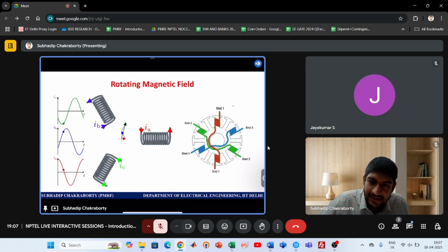And just for animation, we have seen in the previous week also the phasor additions of the MMFs. The currents are creating the fluxes, and then the MMFs add in space, and its strength is constant with time, not varying. Obviously, the magnetic strength depends on the amplitude of voltages that you supply to the coils, and obviously they are balanced.